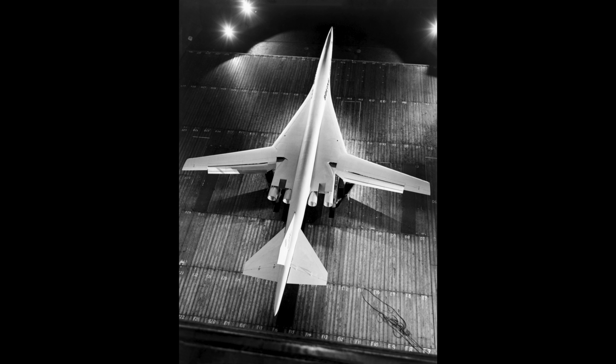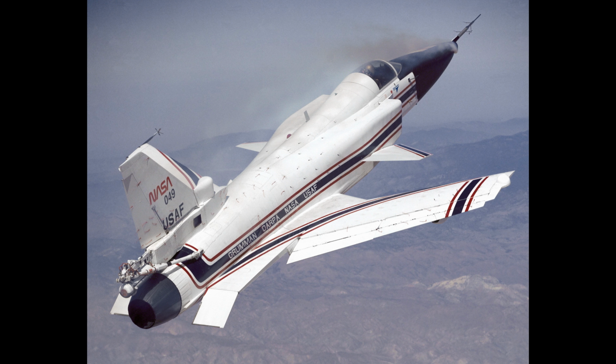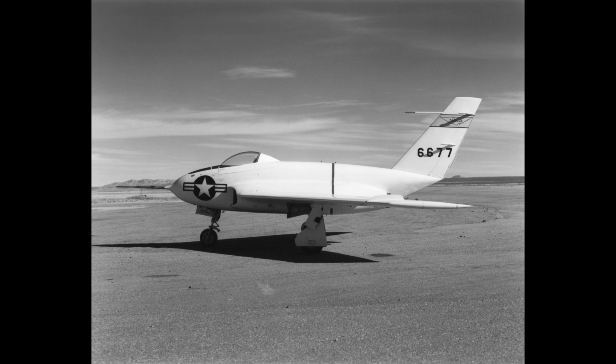Another cool trick that engineers use to make planes fly faster is swept wings. Swept wings are wings that are tilted either forwards or backwards, although right now I will only be talking about wings that are swept backwards. When wings bend air, it accelerates. This acceleration can cause the air to exceed the speed of sound, even if the actual fuselage of the plane has not exceeded the speed of sound. The speed at which that occurs is called the critical Mach number.